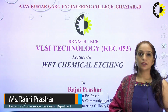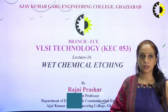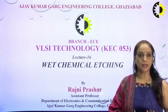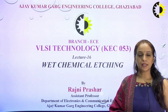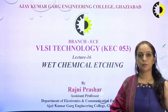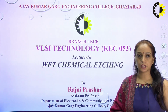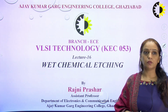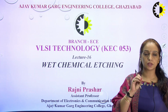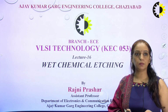This subject is basically dedicated to the fabrication steps which we are going to follow in the processing steps of the fabrication of any IC, right. So in the previous lectures we have created the silicon crystal with the help of the CZ process, and then with the help of oxidation the oxidation layer will be grown, and with the help of the photolithography process we have created some windows where we have to diffuse some atoms or other impurities, right.